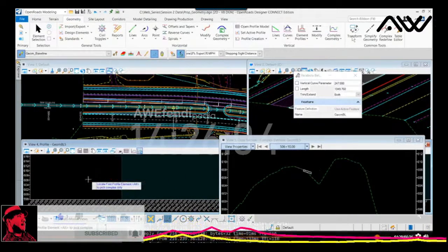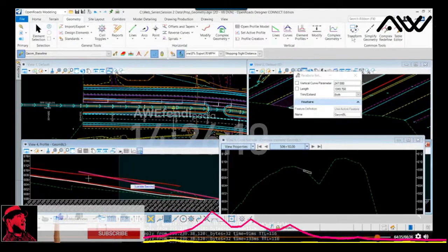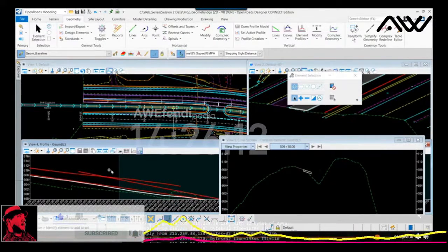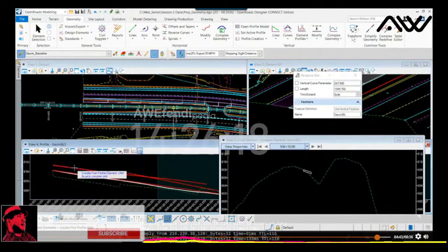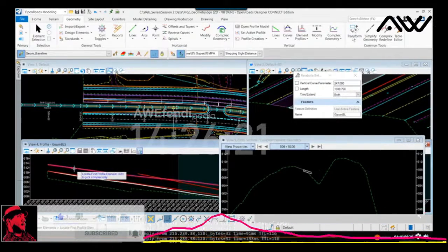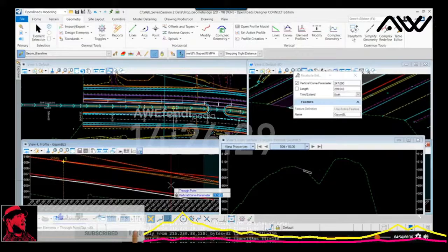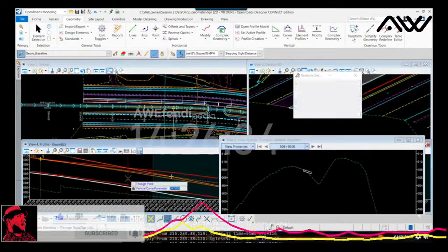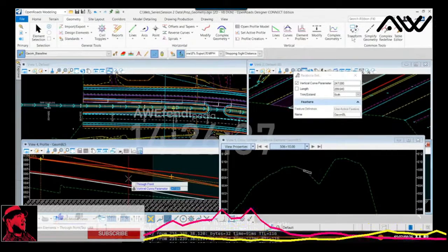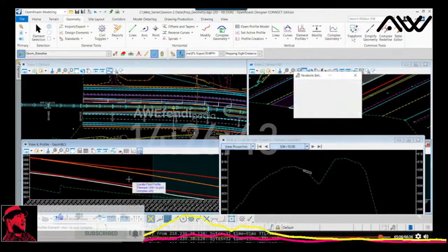So as I zoom in, bear with me, I'll select each of those elements. Let me select each element. Let's back out, make sure I've got there. I want to be sure and select the geometric element and place that arc. Be sure you select the geometry that you created, not the graphical representation of the pavement. Now at this point, my K value is at 247. It's locked based off the design standard I have placed. So I'll data point through the prompts, and now I have that vertical control line in place.